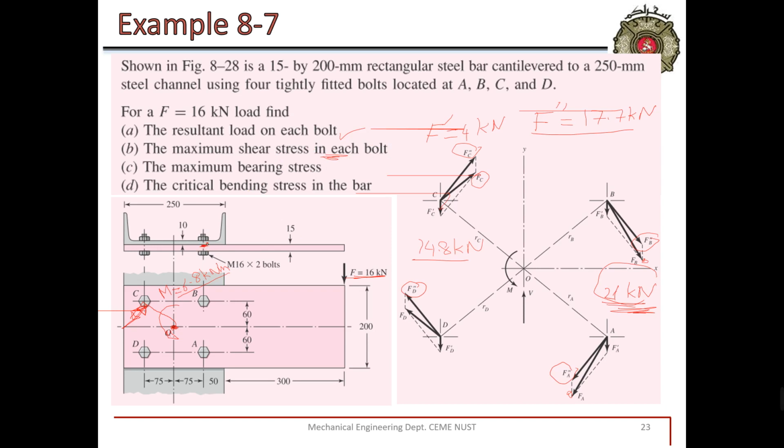In the book, if you see, they have calculated a lot of things. For example, what they have done in the book. This is the total length of the bolt. This is the bolt head. From there, they calculated thickness 1, 15, and thickness 2, 10. So we have the thickness of material 1, the thickness of material 2. Then we have one nut. Then we have 2 extra threads. So it will give us the total length of the bolt.